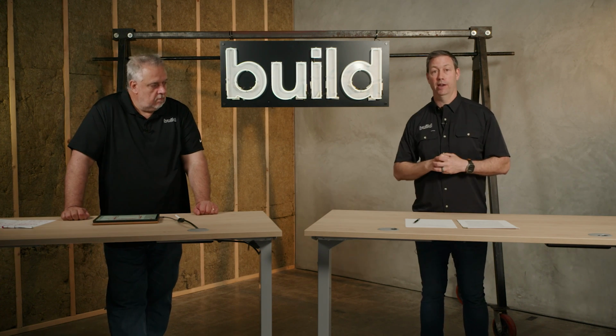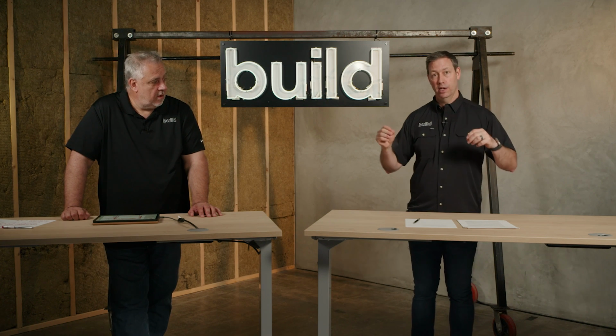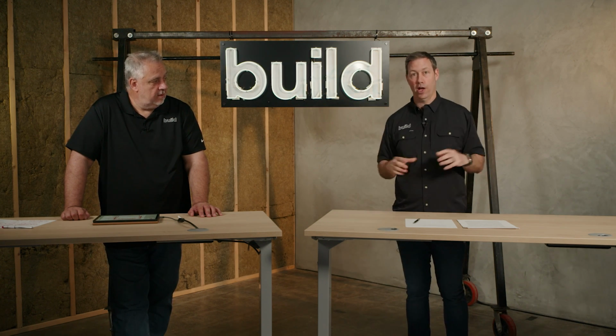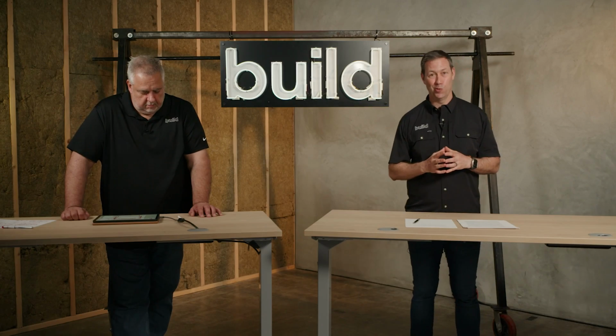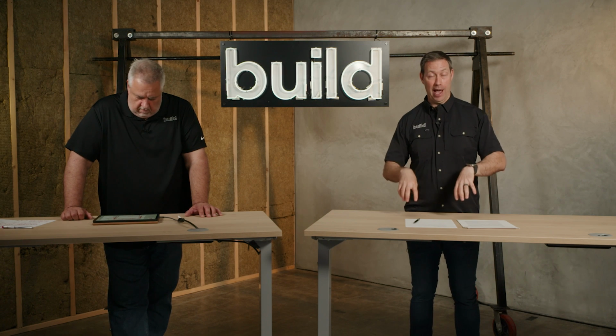That tends to be in attics in Texas. And that really goes against this concept of separating the inside from the outside and maintaining that continuity. For example, if that HVAC equipment was in that attic space, which was outside, and were to leak some air out of the ductwork, and all ductwork is somewhat leaky, now I've depressurized my house. And we know that nature doesn't like a vacuum. So any air that's leaking out of that ductwork is leaking out of the house.